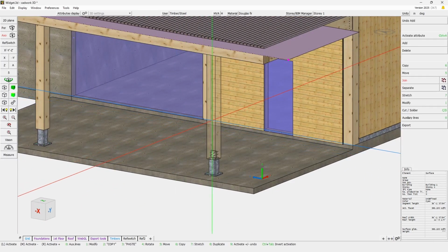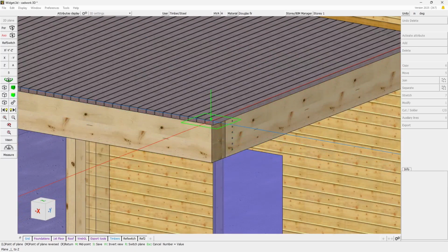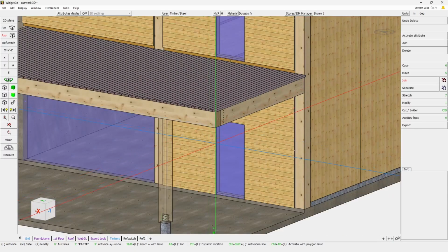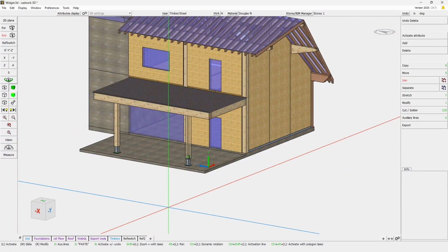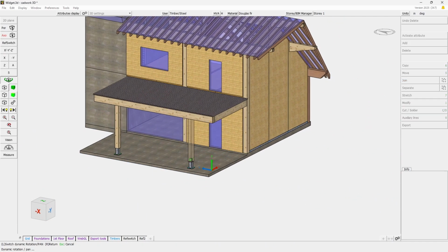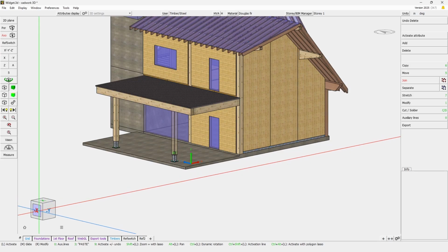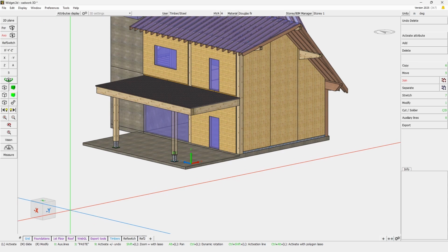So I went from a 2D plane aligned with this, on this one, with a single click, without having to go back in 3D, selecting my plane again, and placing that once more. So I hope this widget will be a great help for you, either to orient your model, or simply to improve the way you are working and going from one 2D plane to another.